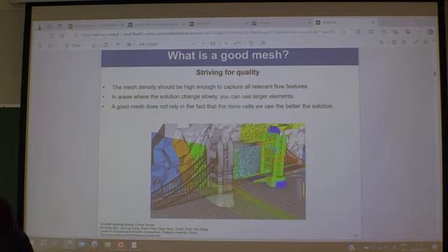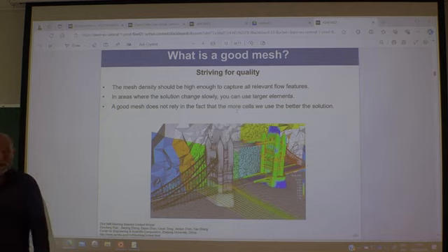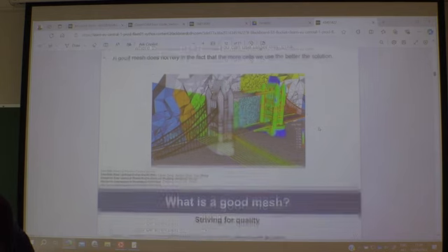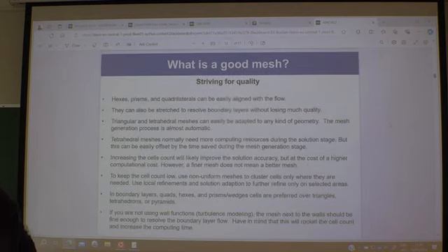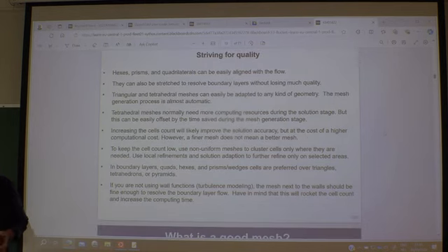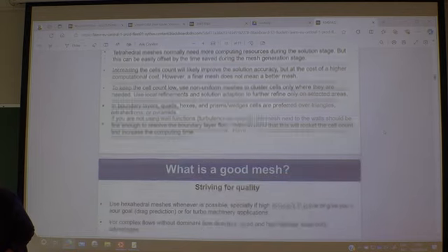So it's not necessarily the case that more cells gives a better mesh. So be aware. As you now know, like with the Y plus problems for a turbulent case, if you're using wall functions, then you have to use a coarse mesh close to the walls, or else you risk destroying the theory for using wall functions. I think it says the same.